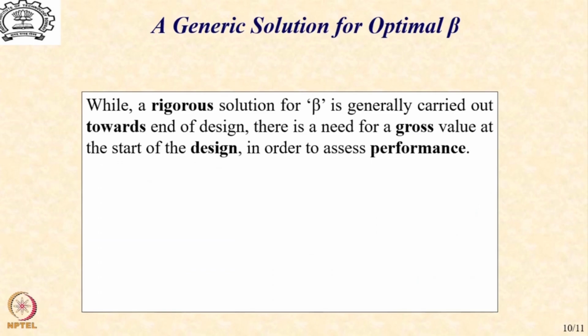Of course, such an analysis would always be carried out, even for the simplified case of a constant burn rate, in a more rigorous manner towards the end of the design through complete nonlinear simulation of equations and numerical solutions. You will find that at the initial stages of design, when you are trying to size the rocket and you want to understand how much loss would be there because of gravity and drag put together, so that you can appropriately put the propellant and the ISP correspondingly as part of your design solution, you need a kind of a gross estimate of the burn rate.